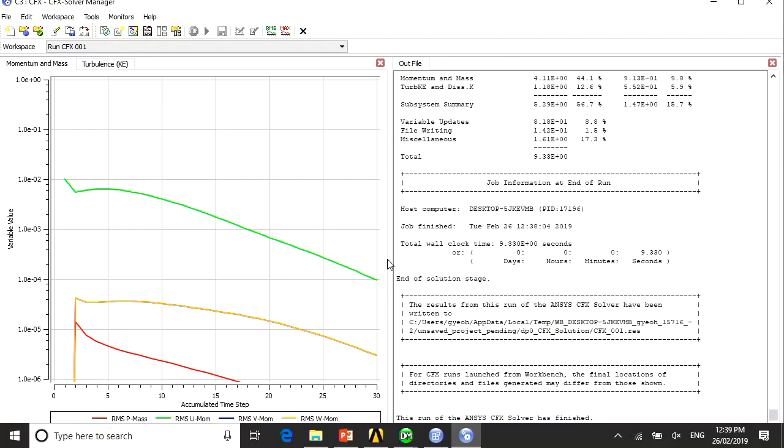I will demonstrate that Fluent will stop at 1e-3 because that is the criterion set for that software itself. So the results can now be viewed in post-processing. The solution converges based on the criteria you set in your preprocessor. If you set 1e-5, it will end at 1e-5. At the moment, you can see that it's well behaved.